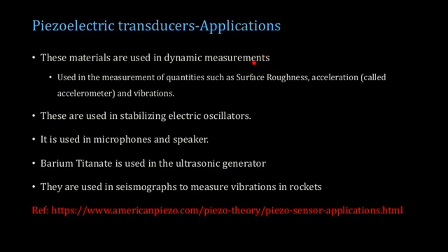Now, some of the applications of piezoelectric transducers are dynamic measurements like surface roughness, acceleration, and vibration. It is used in oscillators, and it can be used in microphones and speakers. So it is used on both sides. Just like a microphone and speaker work on the same principle, here also the piezoelectric effect as well as electrostriction can be used in both microphones as well as speakers. This can be used as an ultrasonic generator, and they are also used in seismographs to measure vibration in rockets. So you can look at this reference and see for yourself the details of the applications.